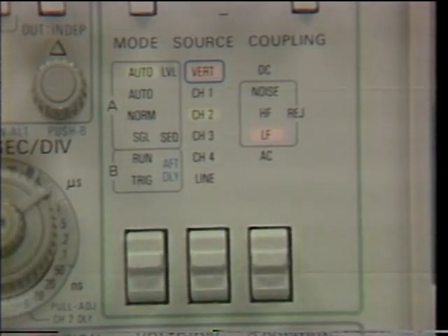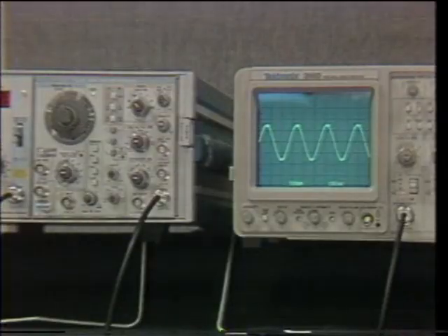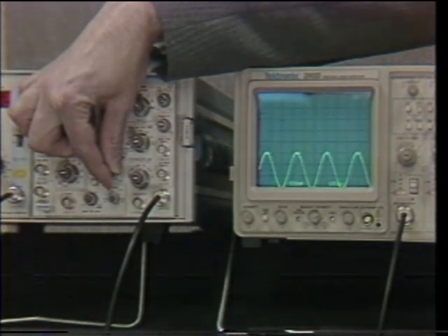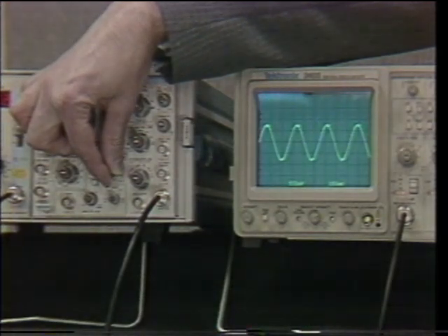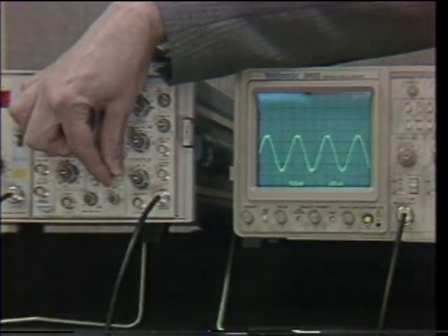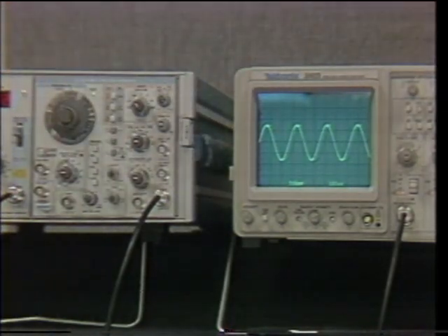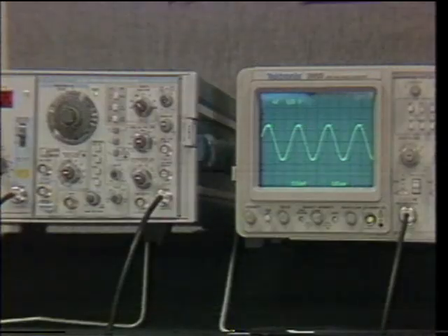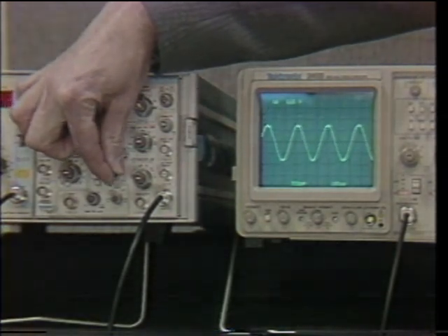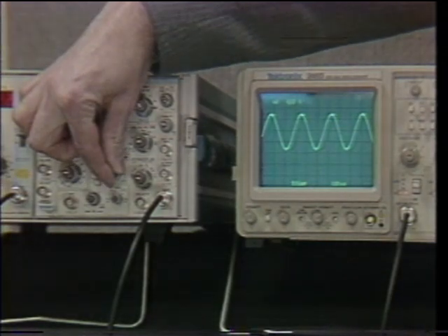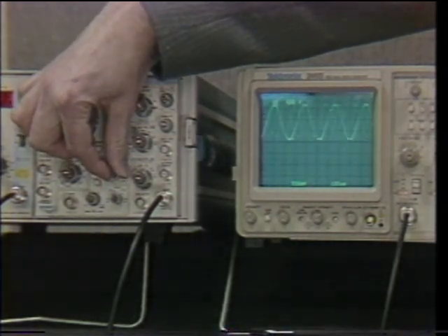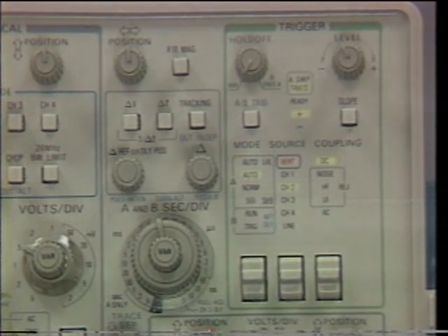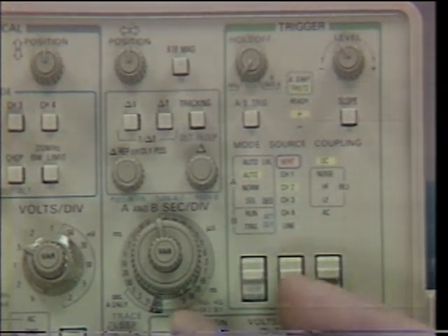The primary application of AC coupling is for signals that are riding on varying levels of DC offset. The AC coupling mode blocks the DC component of the signal and maintains a trigger. In contrast, DC coupling applies this varying DC offset to the trigger circuit as well, and when the signal is offset far enough, the trigger is lost. The A and B triggers share the same controls, however they are independent.